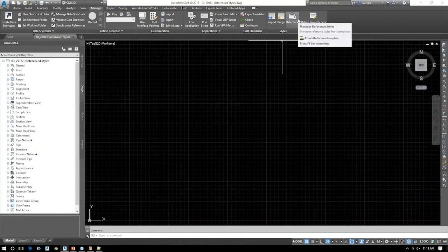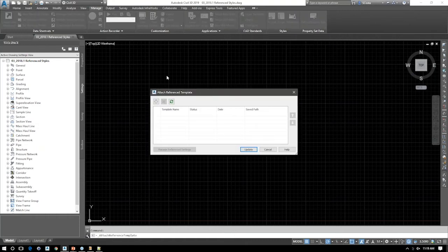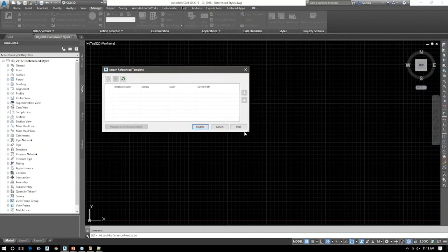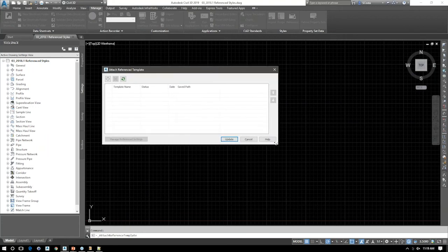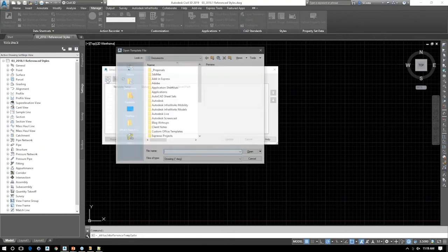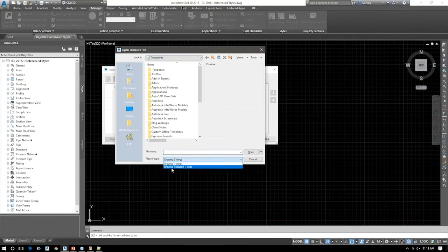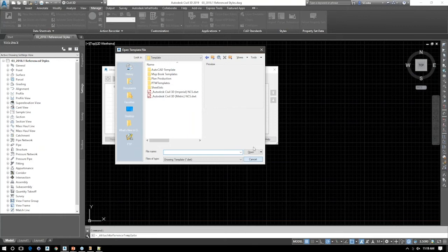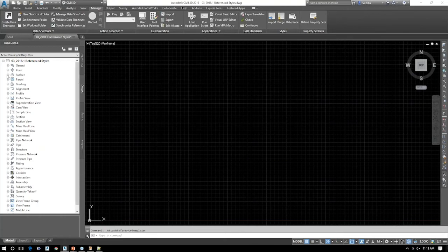That enables you to change the master and have those changes reflected in each drawing that uses it as a reference. Now, this tool isn't the new addition, but what is new is the ability to control the information that gets managed, right? When you reference a template. So this dialog window looks pretty much the same as in an earlier release of Civil 3D. I'm going to go ahead and edit and choose a DWT, and I'm going to, for this example, actually back out, cancel, and just show you that I don't have any styles already set up in this drawing.